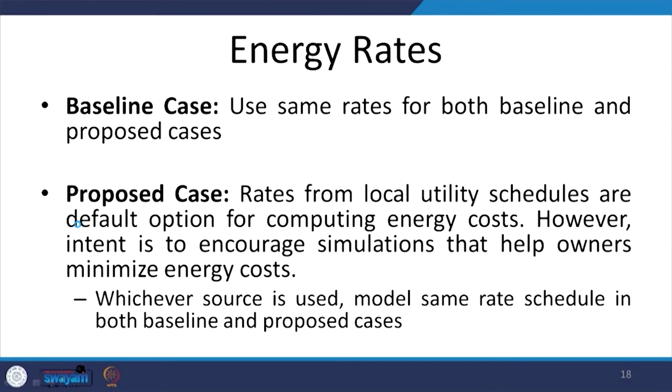However, the occupancy schedules for the controls may vary, but all other process loads will be kept identical for both the cases. In both the cases, both baseline case and proposed case, the same rates will be used, and the rates from the local utility will be used as the default option for computing the energy cost.